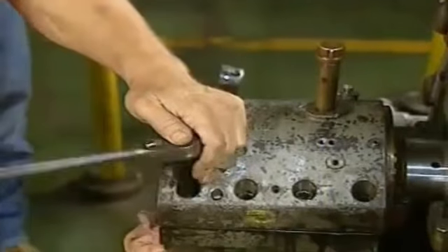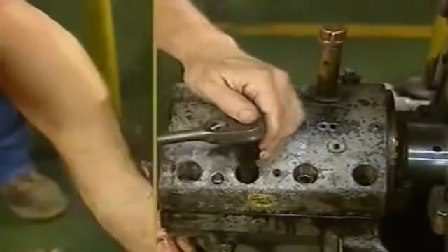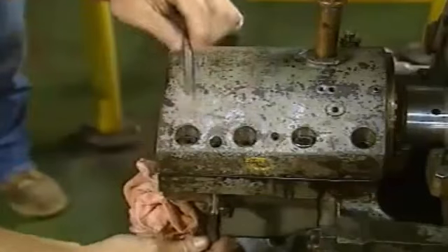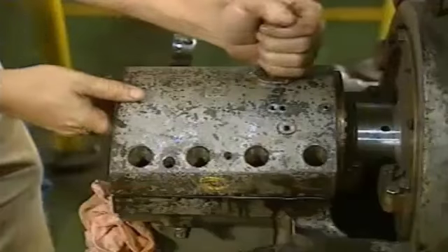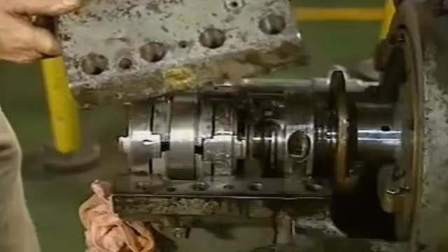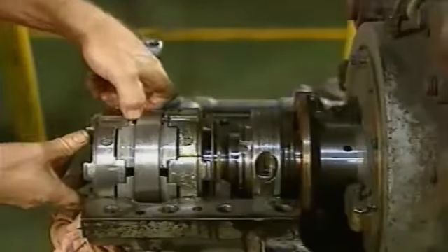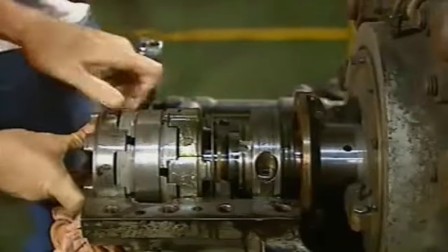To begin, the mechanic removes the bolts from the top half of the bearing housing. Then he removes the guide pins that help align the two halves of the housing. After all the bolts and the guide pins have been removed, the mechanic removes the top half of the housing and sets it aside. In this example, the thrust bearings are removed first before the journal bearing is disassembled.